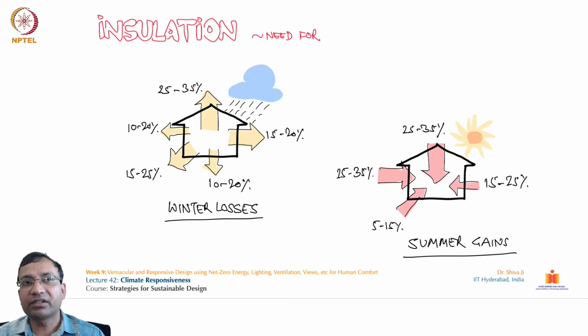Other than dealing with the temperature changes, how we can create an insulator, this surface insulating material on the envelope of our building to reduce the heat exchange. How we can plug the holes and gaps and the other leakage points to check the leakage. There are n number of materials commercially available in the market today for thermal insulation, so we must choose them depending upon the uses and application.